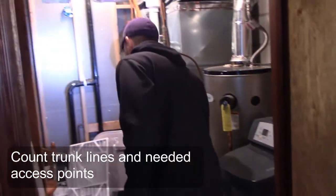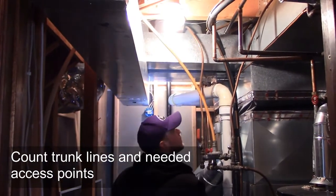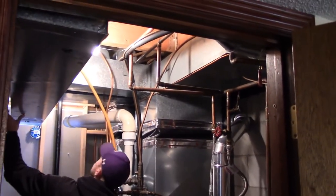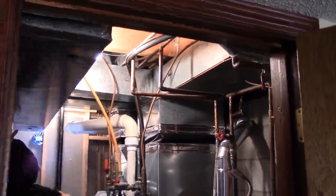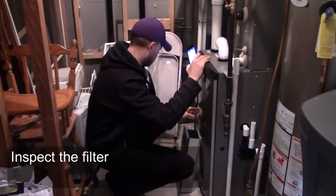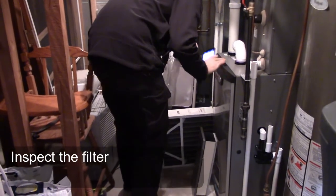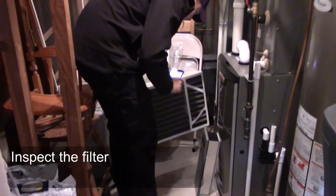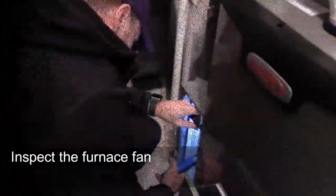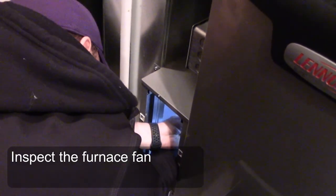Check and count trunk lines in both the supply and return side. Most trunk lines are visible from the furnace room, but you may need to find them along the way. Remove and inspect the filter. Plan to install a new filter after the cleaning. Inspect the furnace fan. Take a photo of the fan to show the customer.